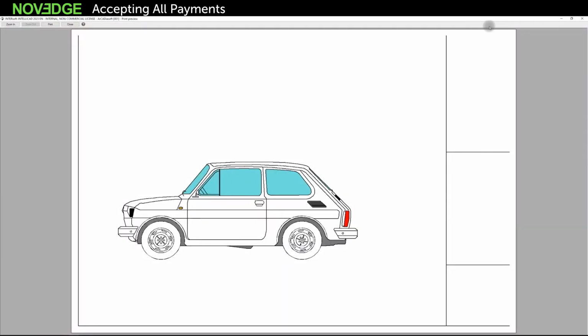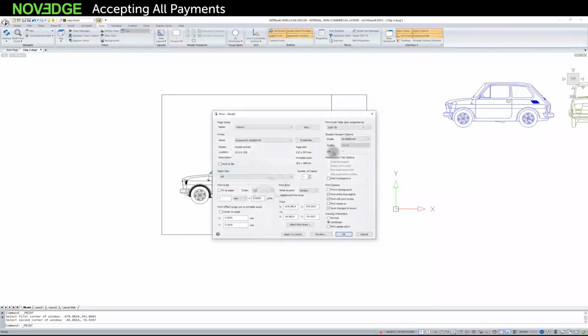You may notice that I have a shift on the sheet to the top and right. This is the size of the sheet, and this is the print area. I didn't take into account the printer's margin. Each printer has a margin, but it cannot be changed in each printer. This printer chosen by me doesn't have this option, so I have to take it into account. The modification of the print area is adjusted for this margin. Changing the printer will change the print area, so remember about this when choosing a printer. Mainly PDF printers have the option to modify the margins, namely zeroing them.